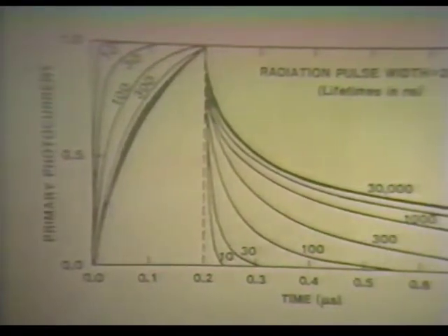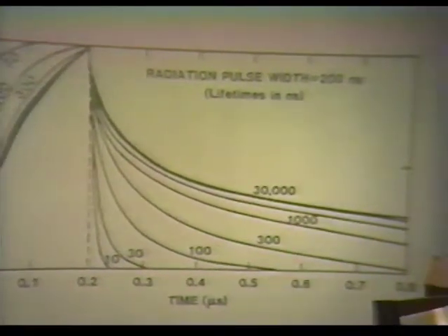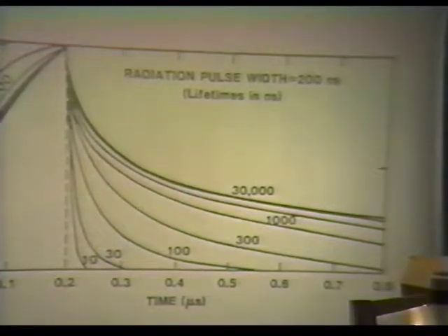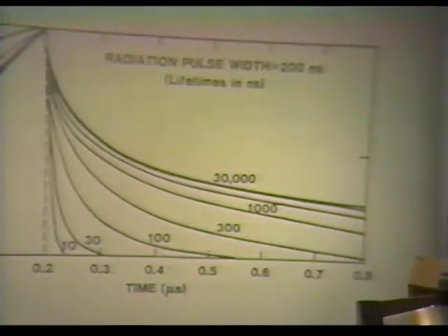What's happening there? The lifetime of your device is long, and it takes a long time for the field to sweep all these carriers you've generated out and restore the device to its initial condition. So sometimes radiation effects may look a little bit like magic, because I can look at this pulse and say, gee, you've got a long lifetime device here. And you say, well, how do I know that? Well, I know that because of the way these carriers have to behave.